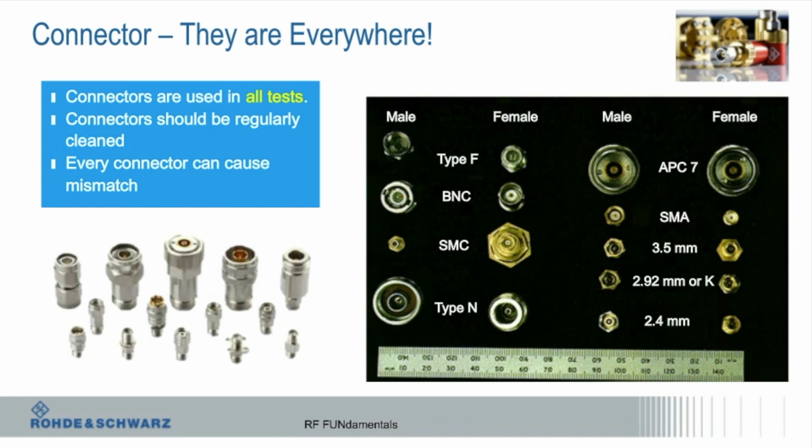I think I started saying this, but we had a 2.4 millimeter VNA, so 50 gigahertz, and a 3.5. A 3.5 and a 2.4 do not mate. If you try to screw them together, they won't mate. But apparently, if you try hard enough, you can make them mate. It's good for one insertion. The performance is really bad. We'll say it's not repeatable, so don't do that. But it's okay for us, because then we get to fix your thing and make you happy again.